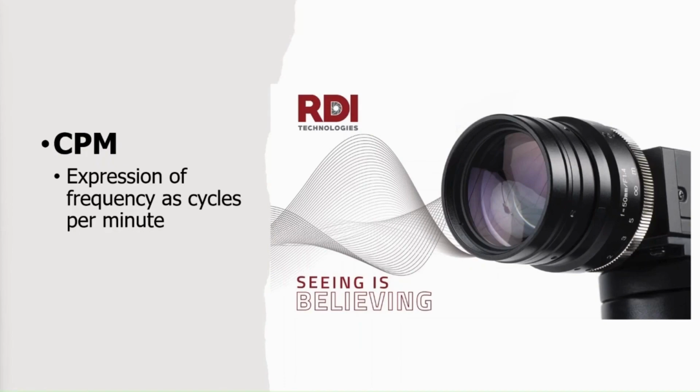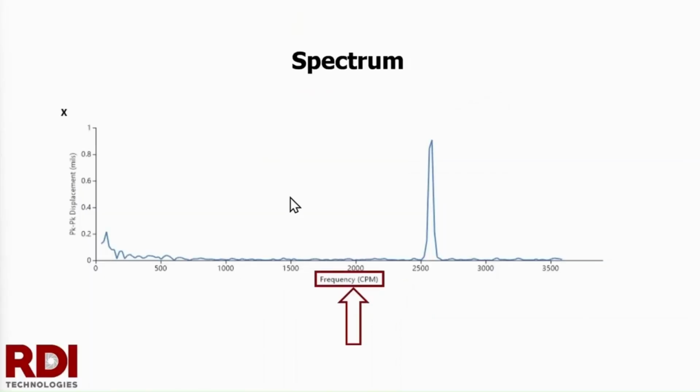Another way to express a vibration frequency is to use CPM, which is cycles per minute. And so in CPM, when I look at the spectrum now, notice the scale has changed and the peak lines up at about 2600. So we'd say the frequency of vibration is 2600 cycles per minute, which would basically be taking the value we had in hertz and multiplying by 60, because there are 60 seconds in a minute.